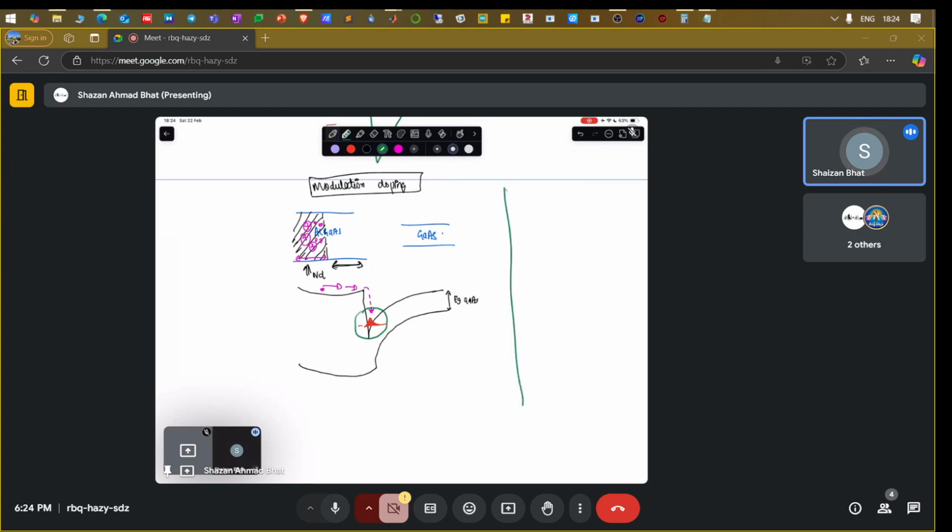It is different from what happens in GaN AlGaN based structures. In GaN AlGaN, if you have aluminum gallium nitride and gallium nitride and you combine them, the electrons come from the surface states of the GaN. How do they come about? Because AlGaN and GaN are highly polar materials, and there exist two types of polarization: spontaneous polarization and piezo polarization.